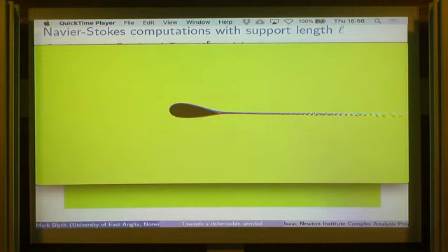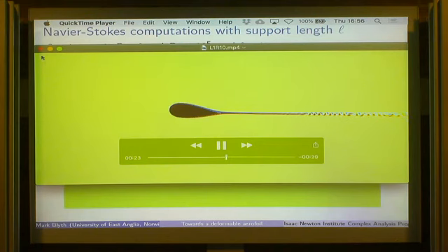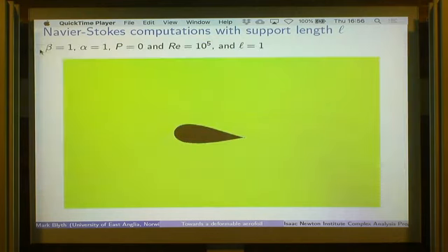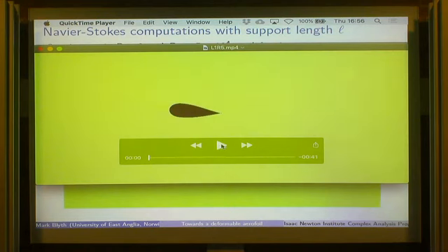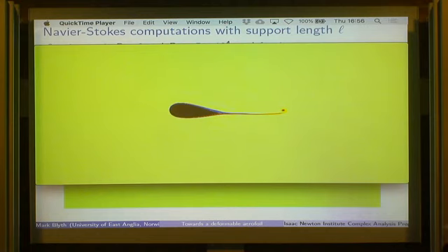Really, the thing to take from that video is that it just looks better than before. There's not so much separation. We want this thing to look as closely as possible like a potential flow. And finally, let's do it at a slightly different Reynolds number. Again, the colours indicate vorticity, so we can read this as meaning this is a potential flow everywhere except where the colour is located. And the separation off the back of that is worse, but still this is not as bad as it was before. It's not generating such a massive wake, so there is an improvement.